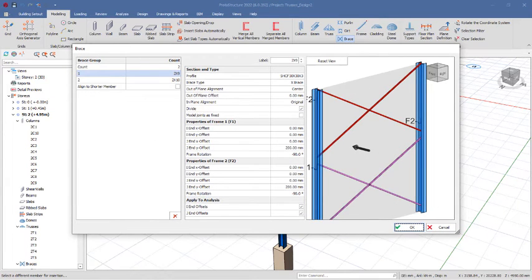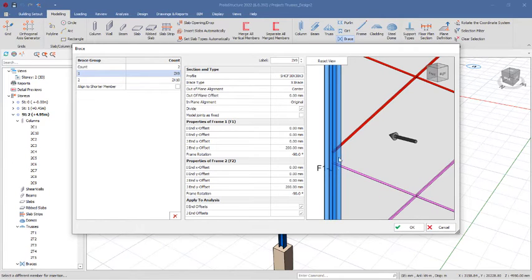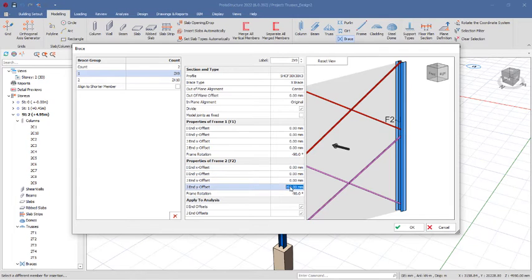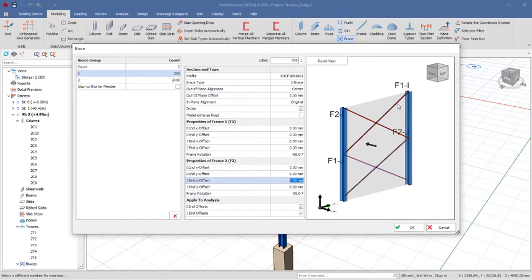So in this dialog, what you just have to do for the count 1 right there, get it selected. So we really want to have this space here because of connections. We want this to be too close, so that is why in the J and Y offset you have to change that to 0 and click outside to bring this close to this member. The same thing applicable here. Come over to this provision, change it to 0, just as I've explained earlier. Then for the I and Y offset, you change it to 300.